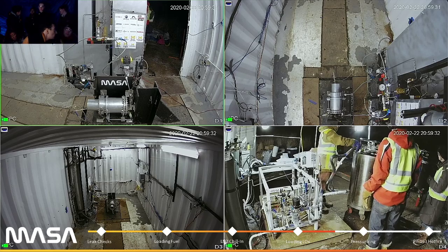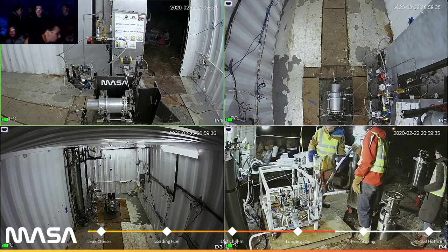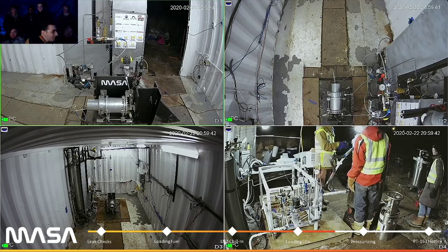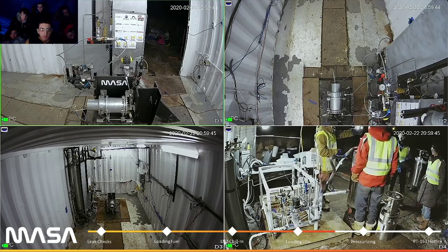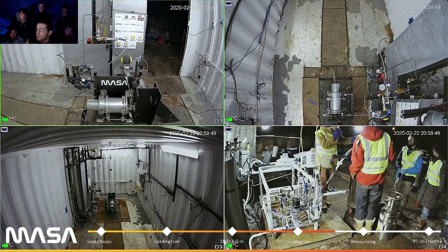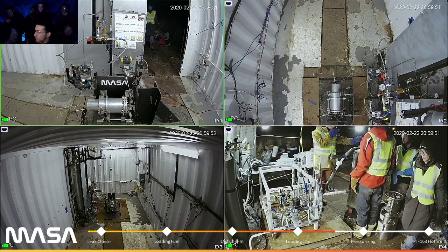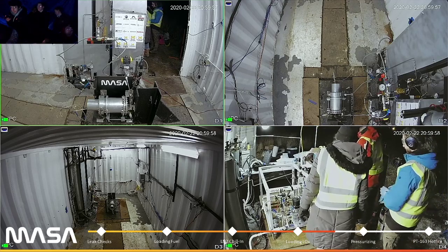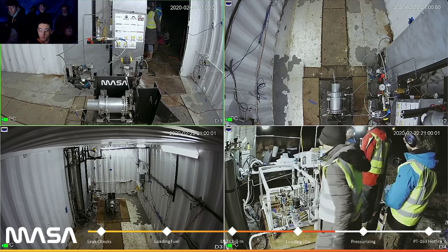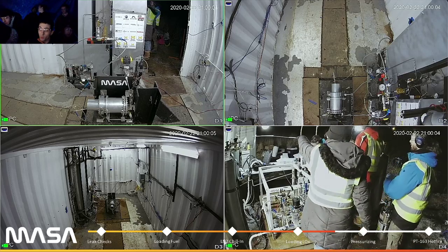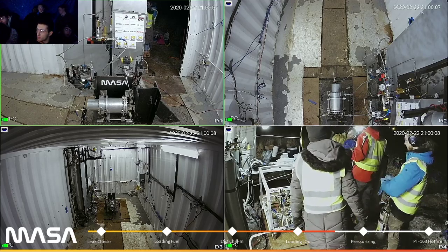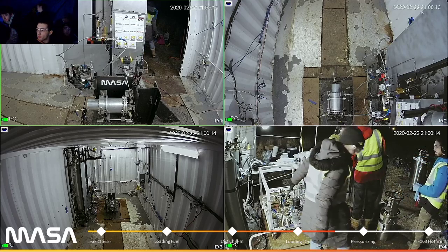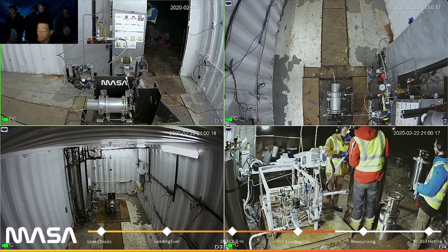As you were asking about the pressure transducer, it insulates from temperature because you usually have about 1 foot, 1.5 feet of an open tube. Basically, you have a small enough tube that the heat transfer through it is pretty low, so at the top of the tube it'll be warm, at the bottom it'll be cryogenic. Since the outside of the tube is exposed to ambient air, that heats it up. It's a really good insulator against the cold gas, so the top of the tube ends up not being cold at all.